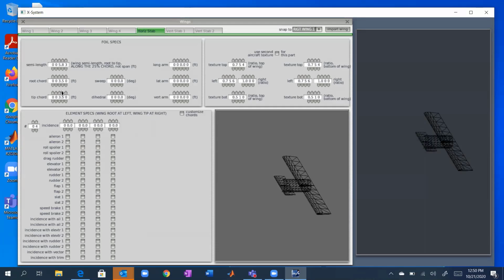And by the way, we're making a glider, but it's based loosely on a Cessna 182. I pulled up the data for that, and that's where I got some of these measurements for the wing size and so on. No sweep, no dihedral, but we do need to move the tail back. And measuring from the picture on the airplane, the tail is approximately located at 22.5 feet aft of the nose of the airplane, which is our datum. If you look on the right, the picture shows you now that's shifted back, right? If we wanted to do a high tail, a T-tail, we could shift this up and put it up high. But this airplane, we're going to leave it lined up.